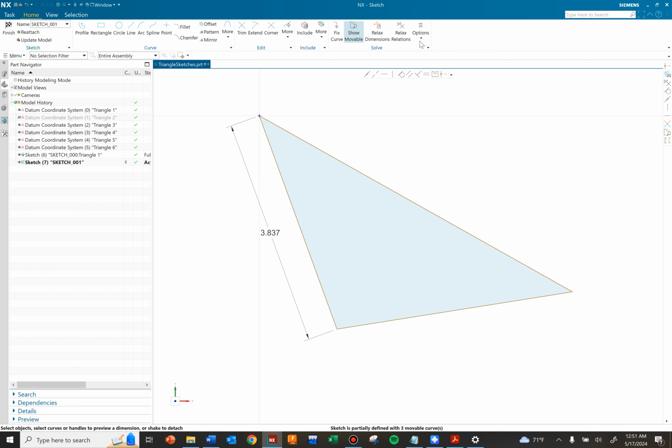If it's off and I turn it on, I have more relations available. If you see this squiggly line and these curves, that means persistent relations is turned on. Notice the last one is the make midpoint aligned. If I turn persistent relations on, now the last one is going to be the make uniform scale.